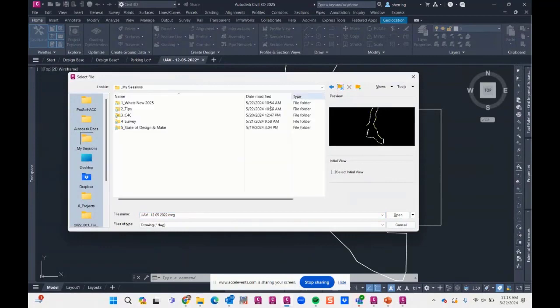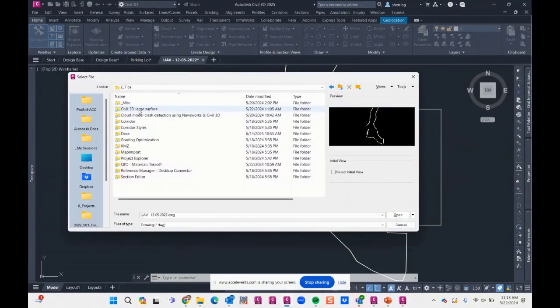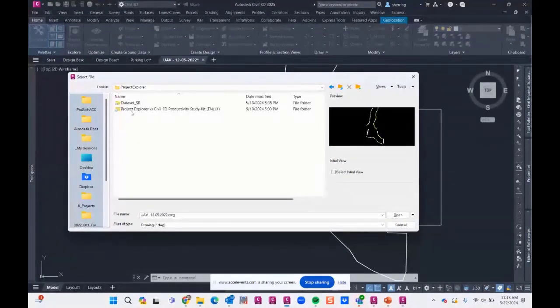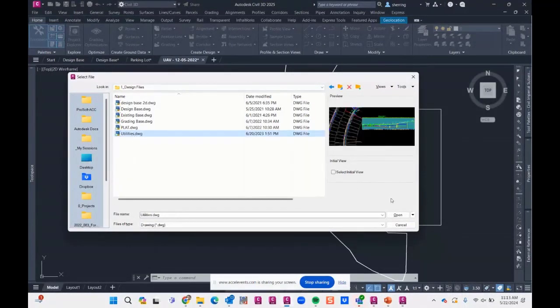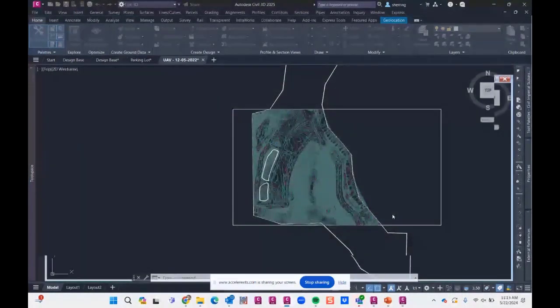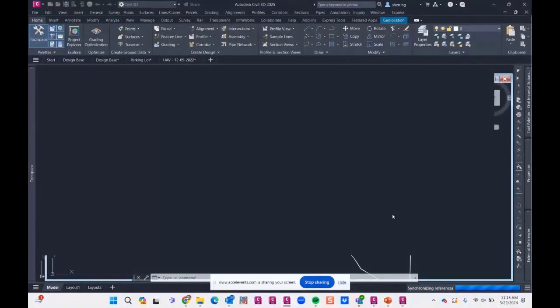So one thing in Civil 3D that you can't do is swap multiple gravity parts. You can swap multiple pressure parts, but why can't you swap multiple gravity parts? It's just dumb. The other thing that you cannot do in Civil 3D is select a manhole over here and downstream 30 manholes and say graded at 0.5%.